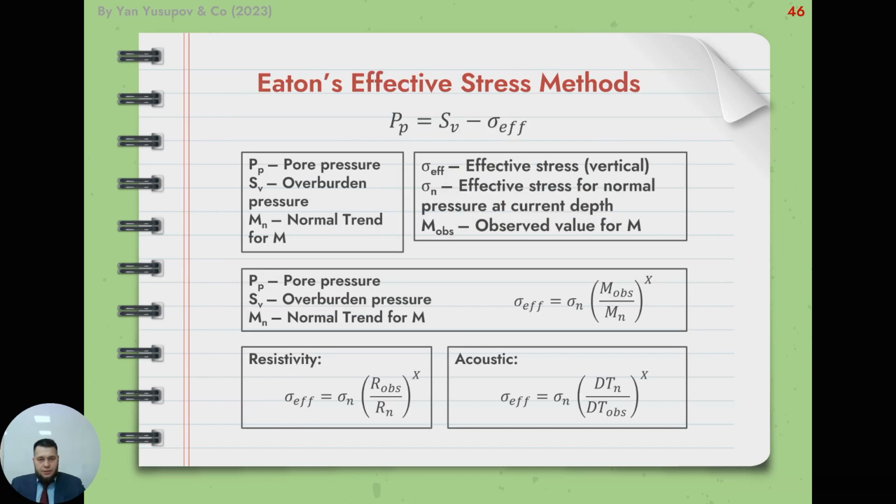This is the simplest Eaton's effective stress method for estimation of pore pressure in shales, which is based on Terzaghi effective stress calculation. Okay, this is the pore pressure that we calculate.